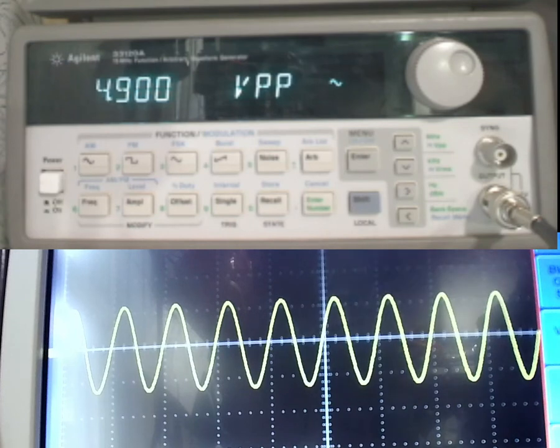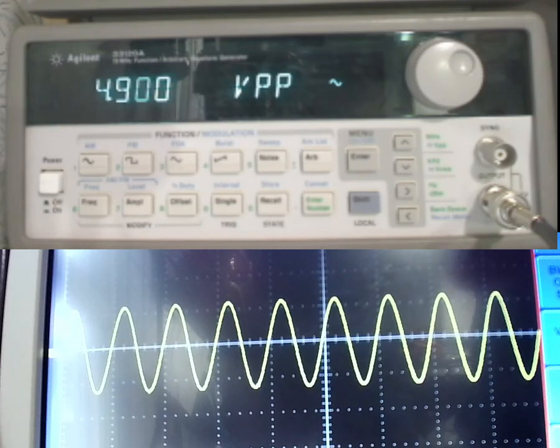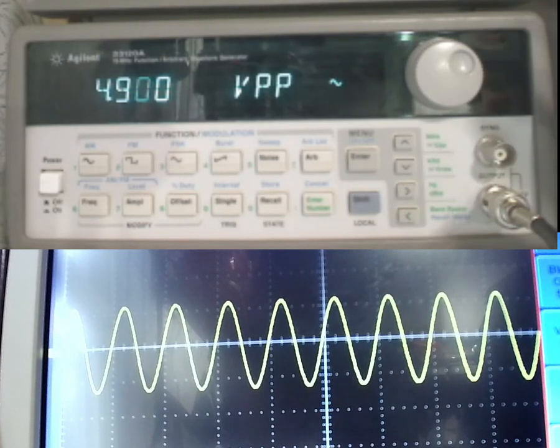You see it's bouncing around a little bit there. It may fluctuate a little bit, but as long as we're pretty close, that's fine. We want to use the reading on the scope, because that's what we're going to be measuring all our voltages by. So we want to make sure that we use the scope to set the voltage and to set the frequency.